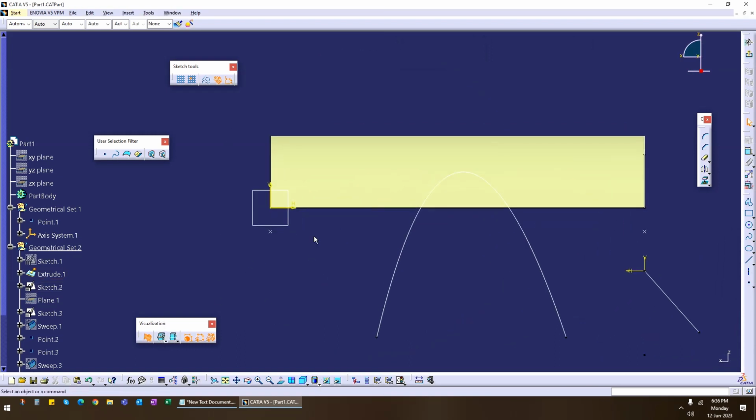And choose this one, and we create a curve. It should be smooth, or we will get some broken surfaces. So it is best that we keep this profile smooth, and then the projection of this profile on the other surface is also going to be smooth.